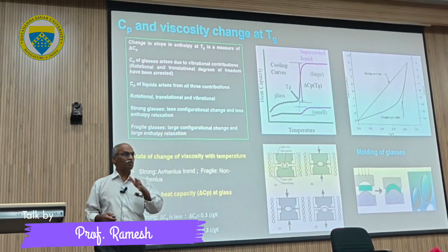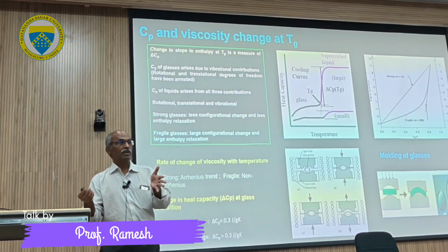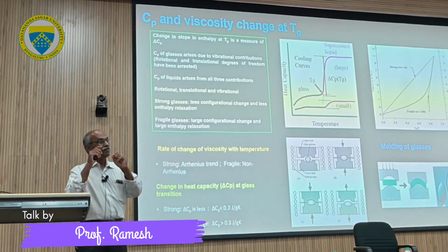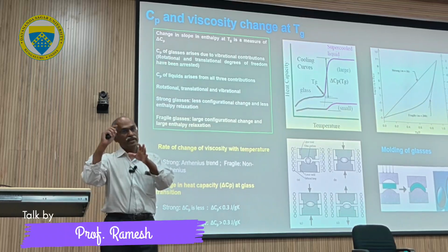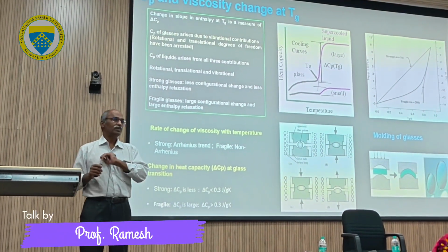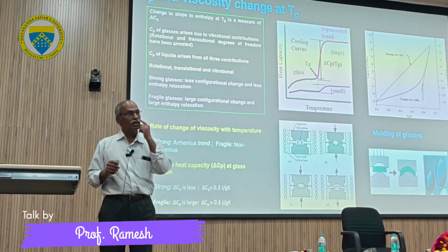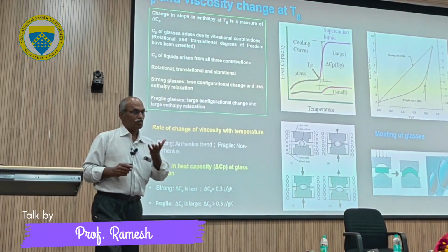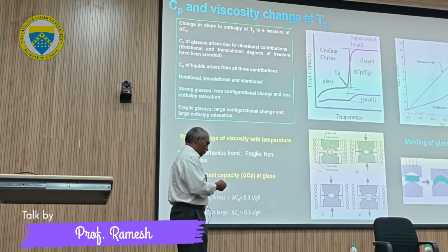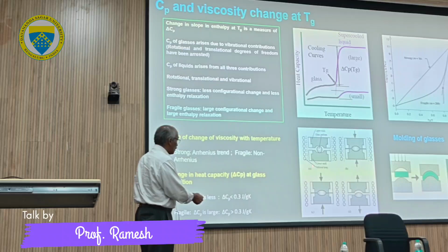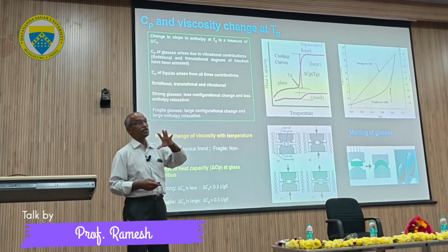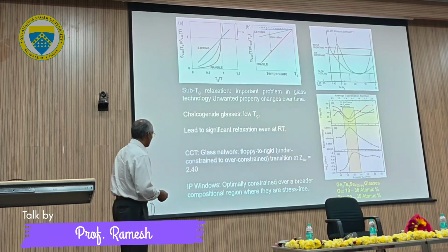For example, germanium is used in infrared transmission. Germanium is one of the well-known materials, but germanium is a crystalline material. So you need to grind them, which is very expensive, polish them, and take them to a lens shape. In this process, you lose a lot of material, a lot of labor, and it's also poisonous, right? So any chemical is poisonous. To avoid that huge laborious process, you can make this mold and get the shape directly. This is one of the advantages of glasses. At the glass transition temperature they soften, and that is exploited for these applications.